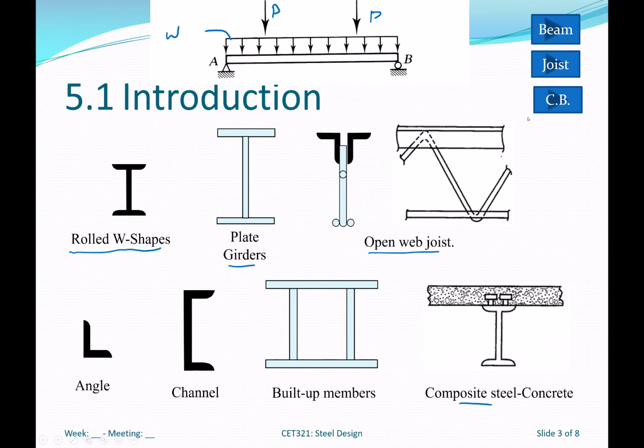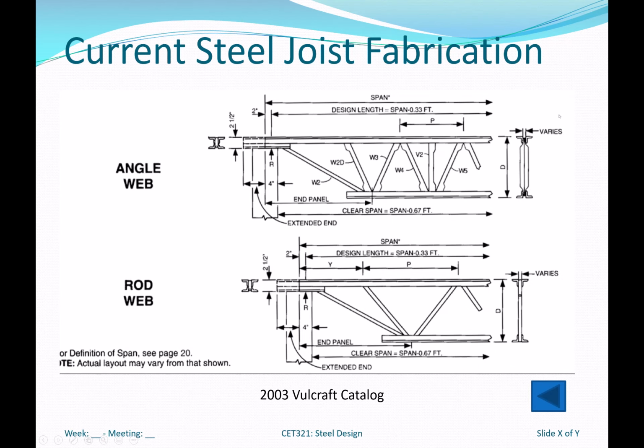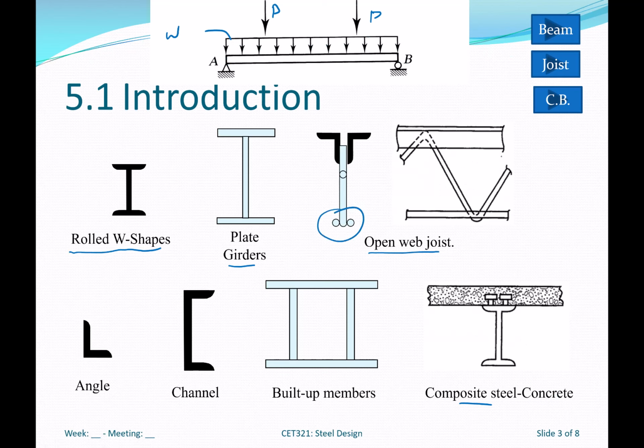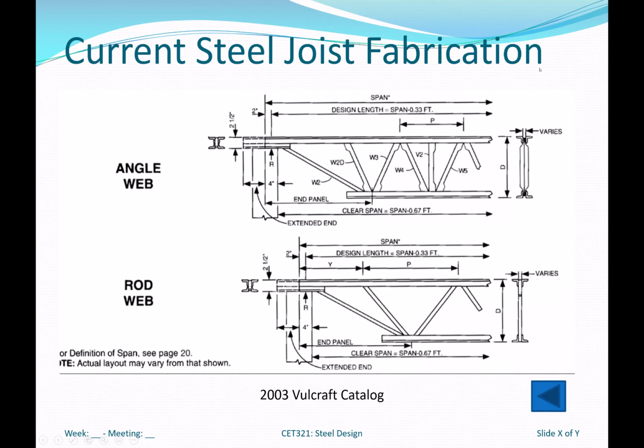All right. So another one that you'll see often is steel joist. Again, steel joist, more like a truss. Couple different methods of fabricating. And again, I don't particularly care for this picture here because it has this round bar bottom chord. This type of steel joist hasn't been fabricated since the 1960s or 1970s. They're more like this with this type of angle.